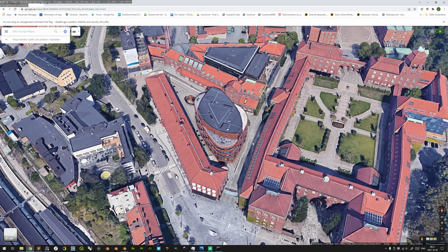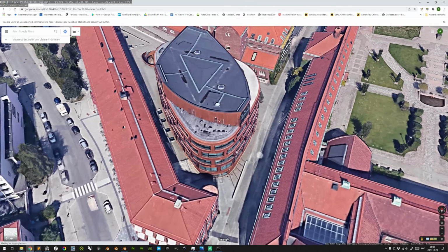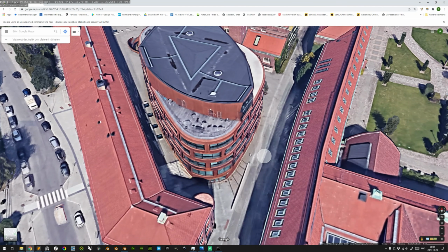And when it comes to extracting these photogrammetry meshes, what you see is what you will get. What is currently presented on your monitor will be the photogrammetry meshes and textures that will be extracted. So if you really want the highest level of detail possible, then you should zoom in until you get that level of detail.